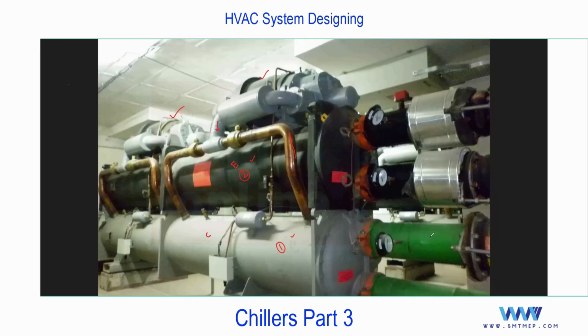Apart from this, this green color pipe, most commonly in actual practice, this is for cooling tower. One is from the cooling tower and one is to the cooling tower. So with the different options you can identify, but without this piping also, easily you can identify the insulated shell and tube is an evaporator. And the reason, because in evaporator, you will find this cooling effect. So to avoid this energy losses, we require insulation for the evaporator. But for condenser, we don't require the insulation because this rejection of heat will add advantage.